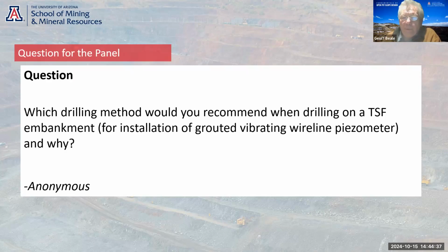Yeah, I think particularly if you're in a sand dam, dual tube or triple tube core is good. And it's an interesting one, about fluid loss. As you probably well know, there are theories that there have been tailings dam instabilities caused by drilling, and you can argue one way or the other. But there are 3 or 4 tailings facilities that I work at where any drilling with fluid is, well, not allowed. I guess that's after Brumadinho and things like that, isn't it? Yeah, exactly.